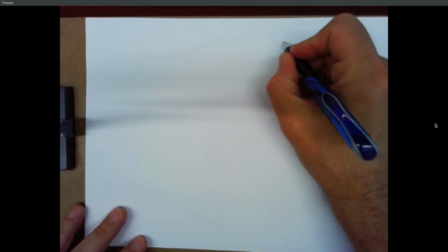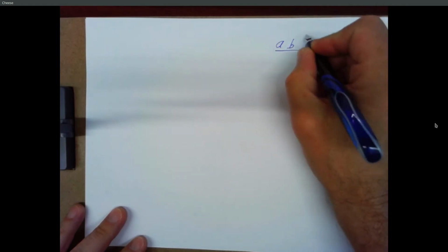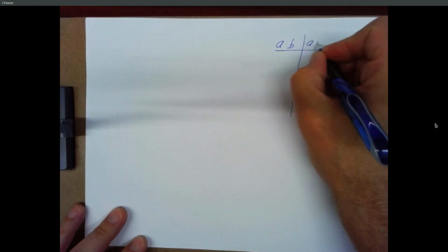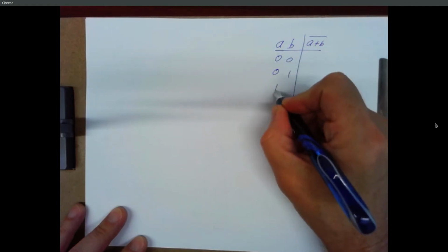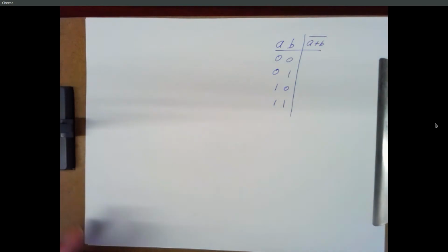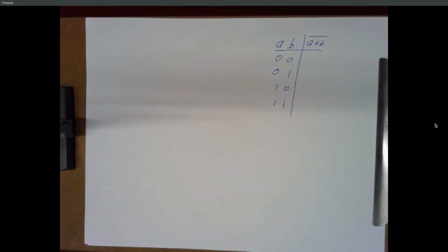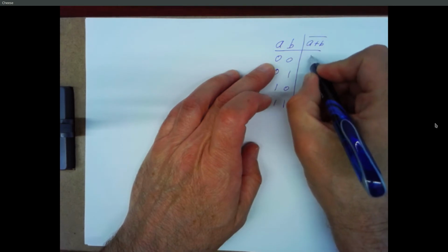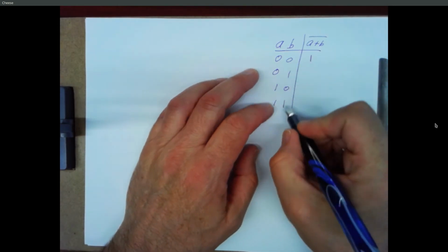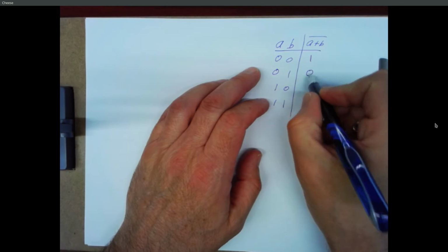And so we want to make a proper version of a 1-bit memory using that concept. But instead of inverters, we're going to use a NOR gate. So let's look at what NOR does. NOR is just the opposite of an OR. So normally the OR of this would be 0, the NOR is 1. The OR of these 3 rows should be a 1, so the NOR is a 0.